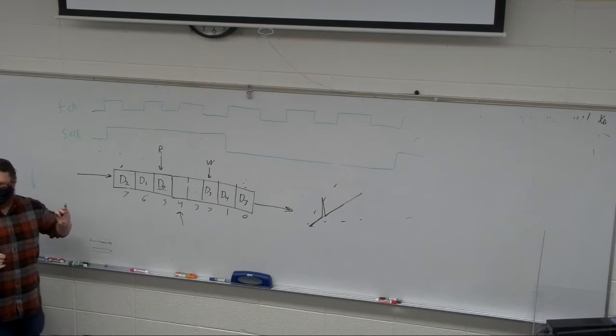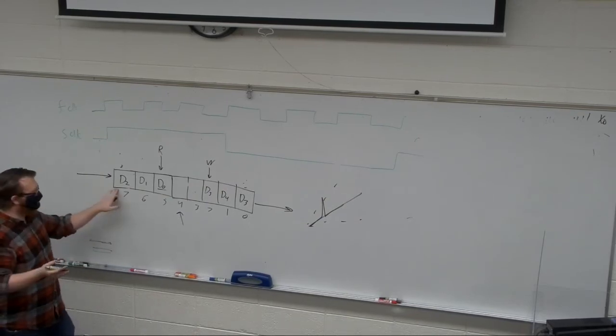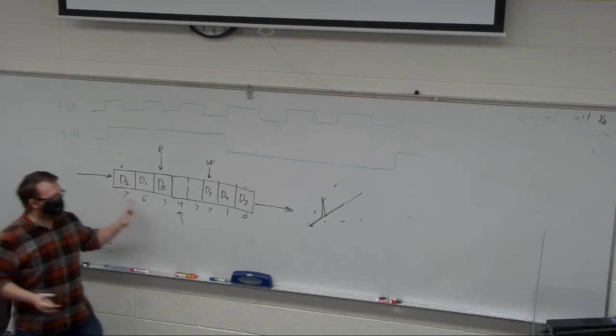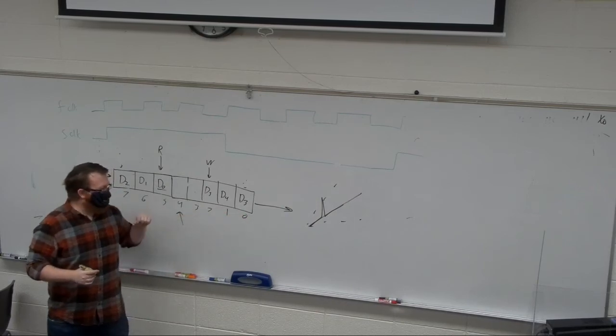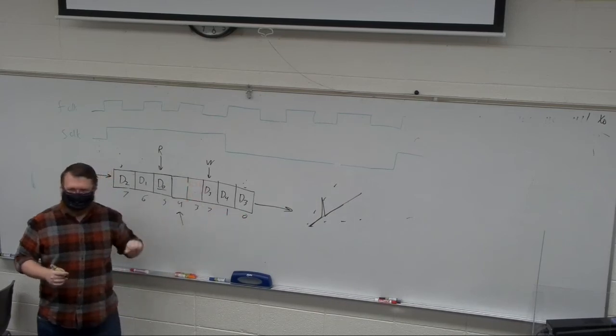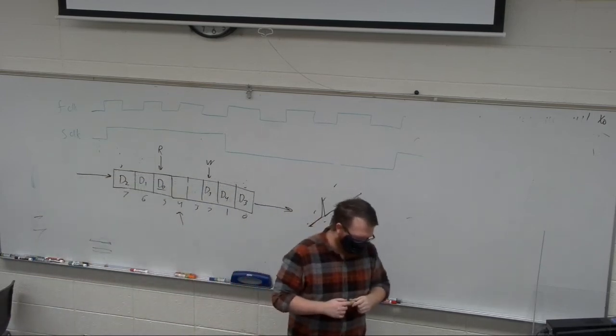Gray code won't do that. Gray code will happily plug along and it changes 1 bit. So worst case, I get this for 1 clock cycle too long or this one clock cycle early, right? So that's kind of the hint if you're designing these yourself: write the indexes in Gray code.